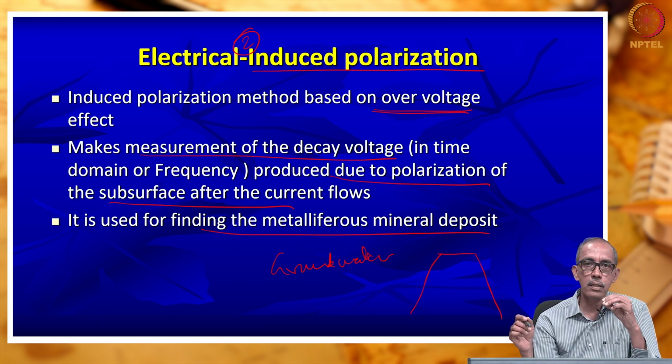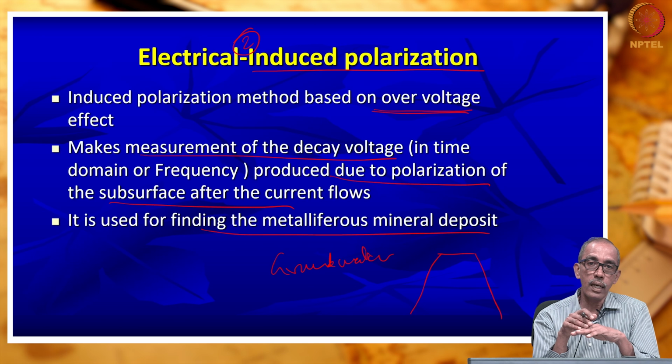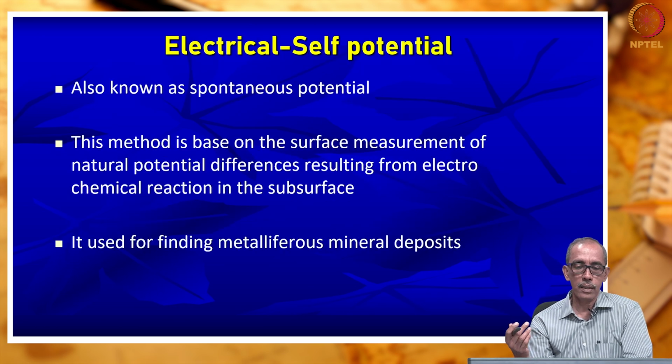Groundwater flow triggers a natural electrical potential. Apart from that, when you induce a large amount of current, the current is retained for additional time due to the groundwater flow. This can be detected by induced polarization method.